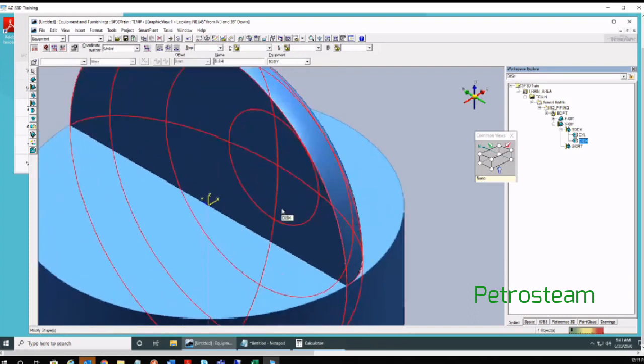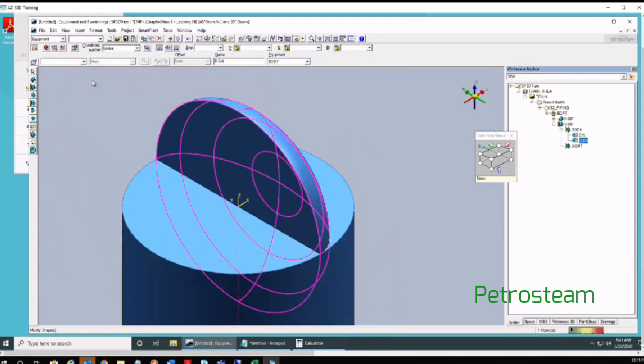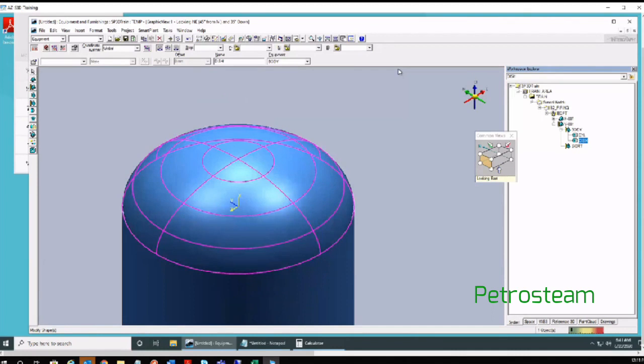You cannot rotate directly there. Once you place, already the dish end is selected, and this also you have to rotate around y axis. Y is already active. With that, use the right arrow mark. Now your dish end is rotated by 90 degrees with right arrow mark.